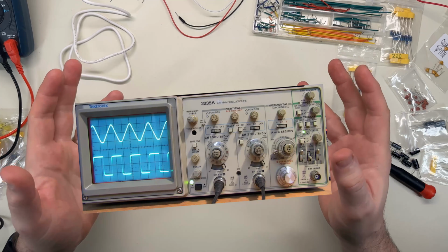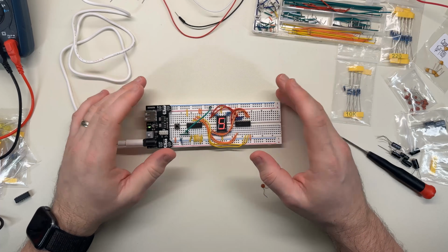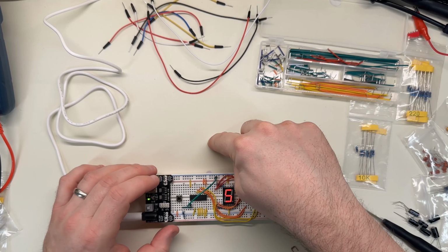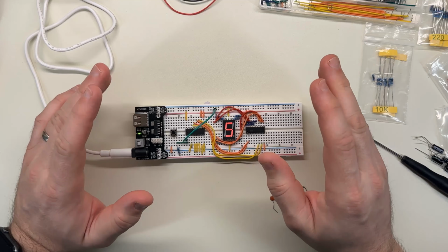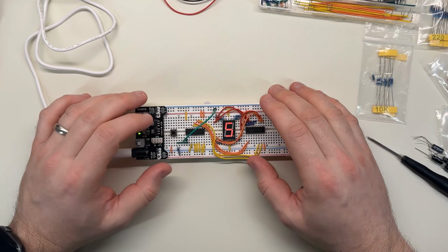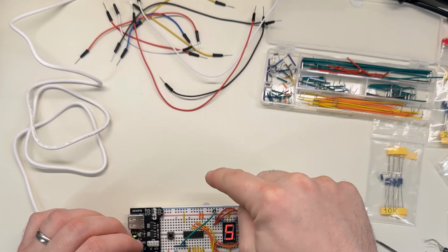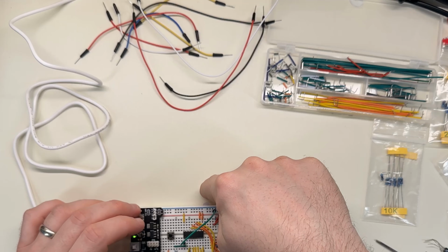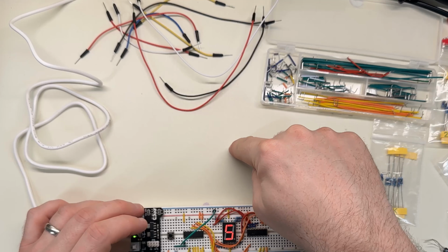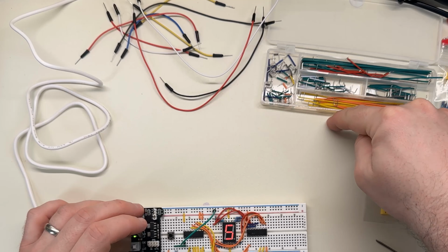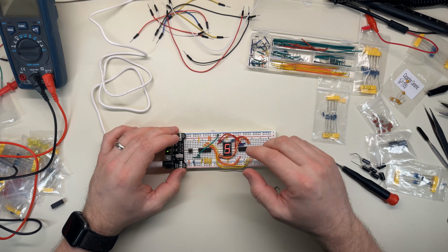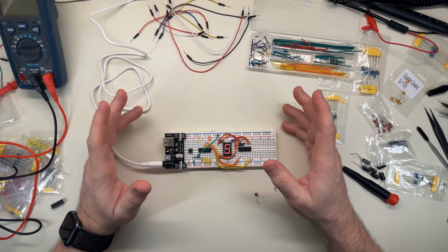If I had an oscilloscope, I could show this pretty easily, but I don't have one, so you can probably imagine it. The oscilloscope measures voltage over time, at very, very quick time slots, much faster than you can perceive, like nanoseconds. If you were to imagine the voltage going through the switch, it might start at nothing and then spike up when I push it, but then it might drop down and do a bit of wiggling before it settles down, or up in this case. That causes the chip to mistakenly think that I pressed the button a bunch of different times.